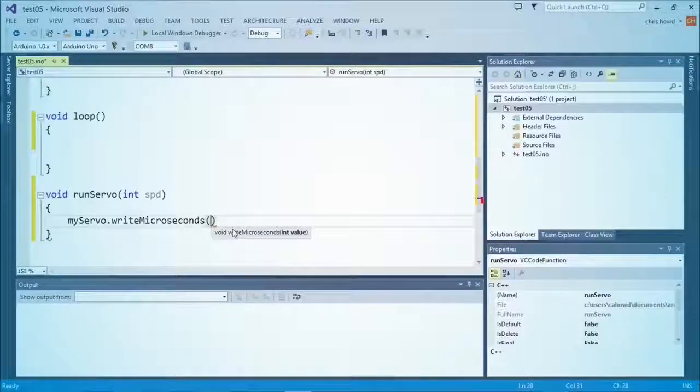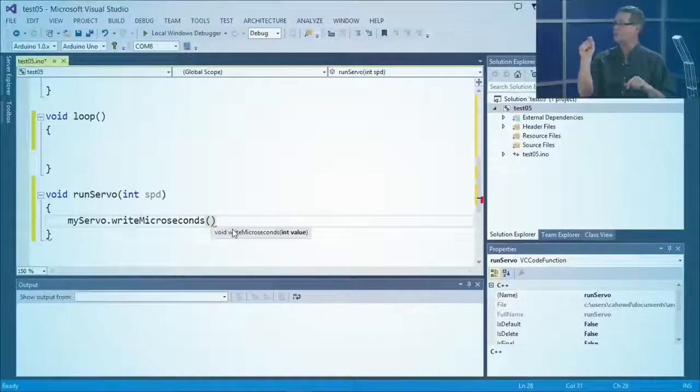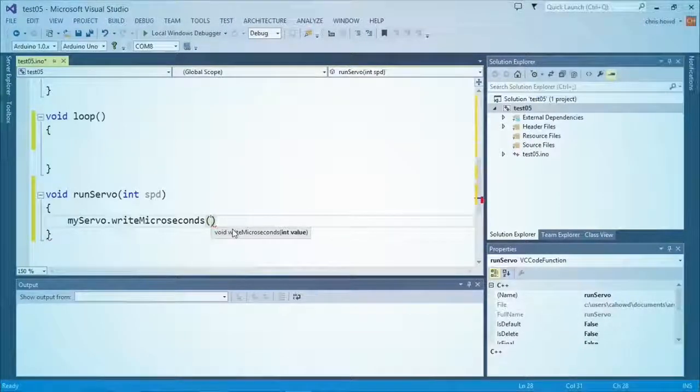Seconds sounds like a temporal thing, but it sounds like we're moving something in space, right? So why is it microseconds? Yeah, it sounds counterintuitive. That comes down to the signal that the servo motors work with, this pulse width modulation. It is, as the name says, a pulse, and that pulse goes high for a certain amount of time within its cycle. And so that duration, while it's high, it's getting positive voltage, and for some of these things, it'll interpret it different ways, but for the longer duration, it's going to go faster, right? I see. Makes sense. So you can do other things with it. With pulse width modulation, you can use it for setting voltage on an LED and make it light.